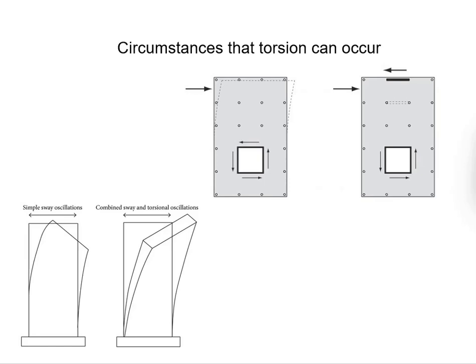Now you need to know that this wind load is actually a variable action, which can be there and can be not there. The magnitude and the directions can differ under different circumstances. In the case that you have inconsistent wind load acting onto the structure, the global structure may undergo slight twist.